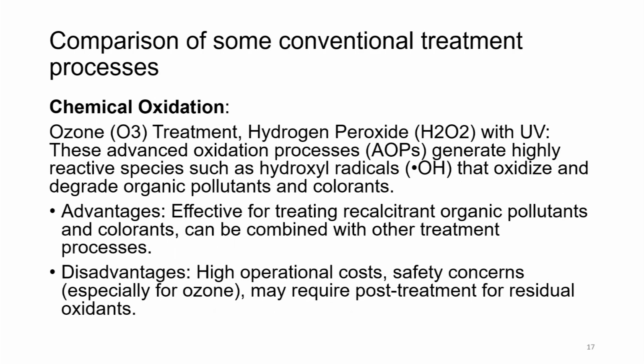Chemical oxidation, ozone treatment, hydrogen peroxide with UV: these advanced oxidation processes, AOPs, generate highly reactive species such as hydroxyl radical, that is •OH, that oxidize and degrade organic pollutants and colorants. The hydroxyl radical •OH is highly reactive.